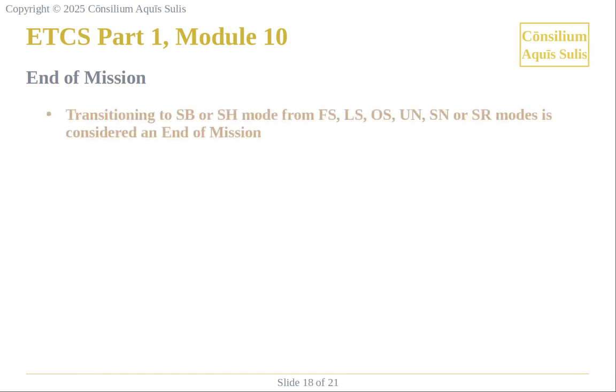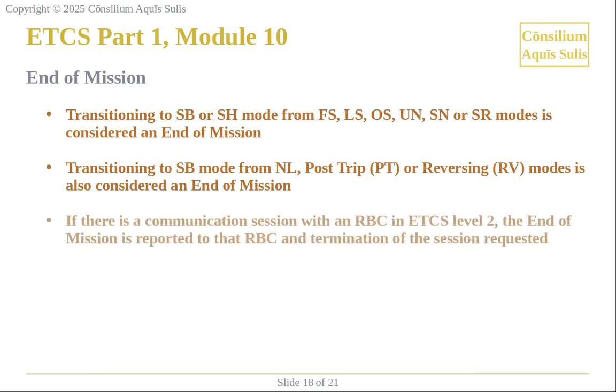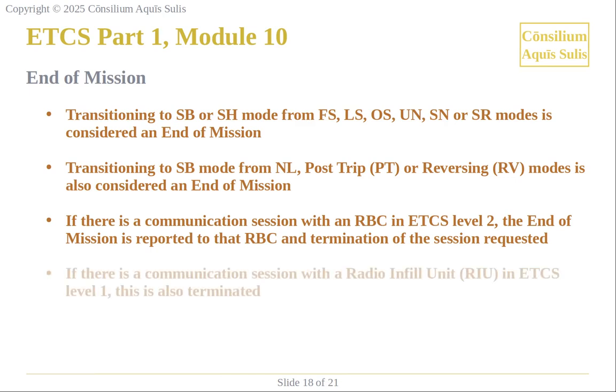Transitioning to standby or shunting mode from full supervision, limited supervision, on-sight, unfitted, national system or staff responsible modes is considered an end of mission. Transitioning to standby mode from non-leading, post-trip or reversing modes is also considered an end of mission. If there is a communication session with an RBC in ETCS Level 2, the end of mission is reported to that RBC and termination of the session requested. If there is a communication session with a radio infill unit in ETCS Level 1, this is also terminated.